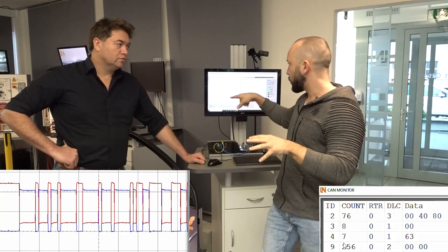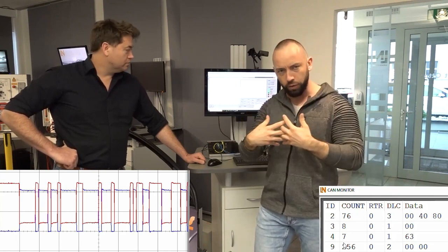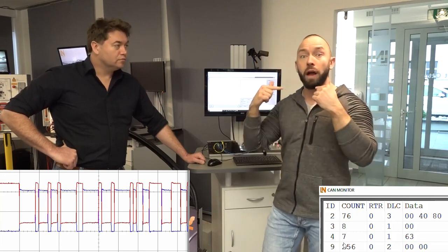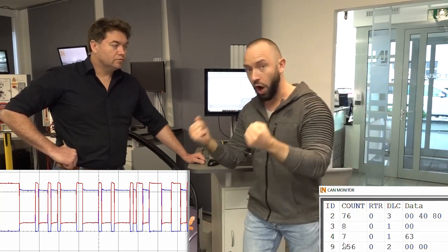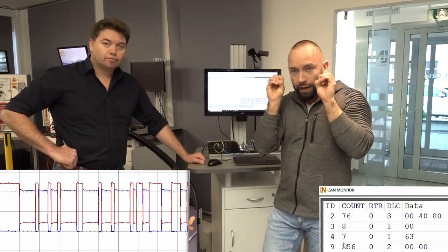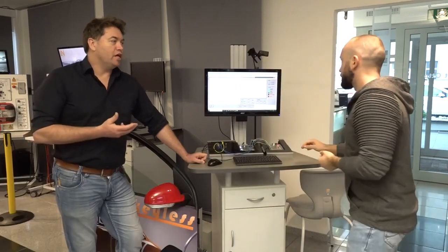But now, because we can send all the different information and it can be taken into account by the control unit for the lights, for example, it says, I have now an emergency brake, a really hard brake, so I will change the control of the lights so that they do not just brighten up, but start flashing. And this is only realizable through CAN bus.